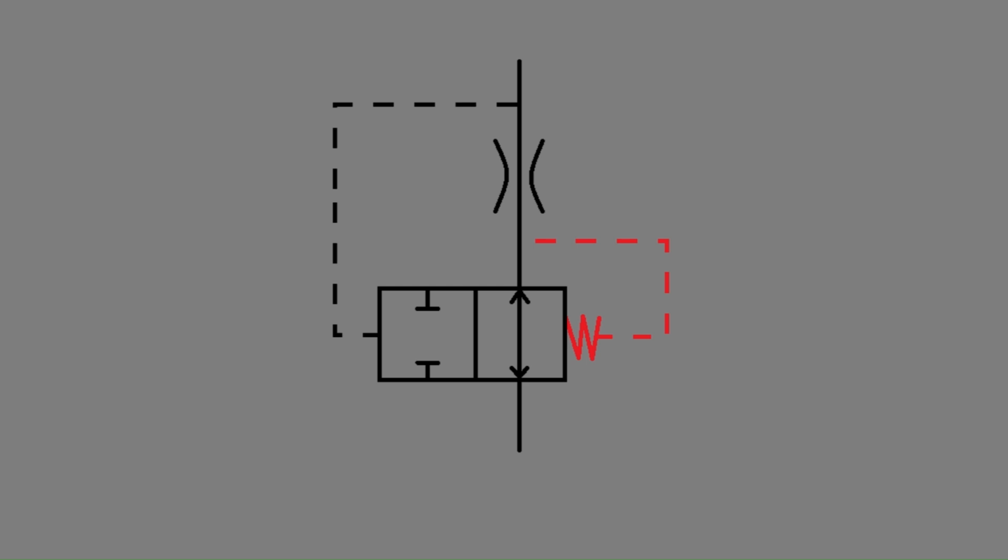If the pressure drop becomes higher than our targeted value, the difference in pressures between the high and low signals will allow the high pressure side to overcome the forces of the low pressure signal and the spring to modulate the valve closed. The pressure compensator will be constantly modulating open or close to achieve the desired pressure drop.